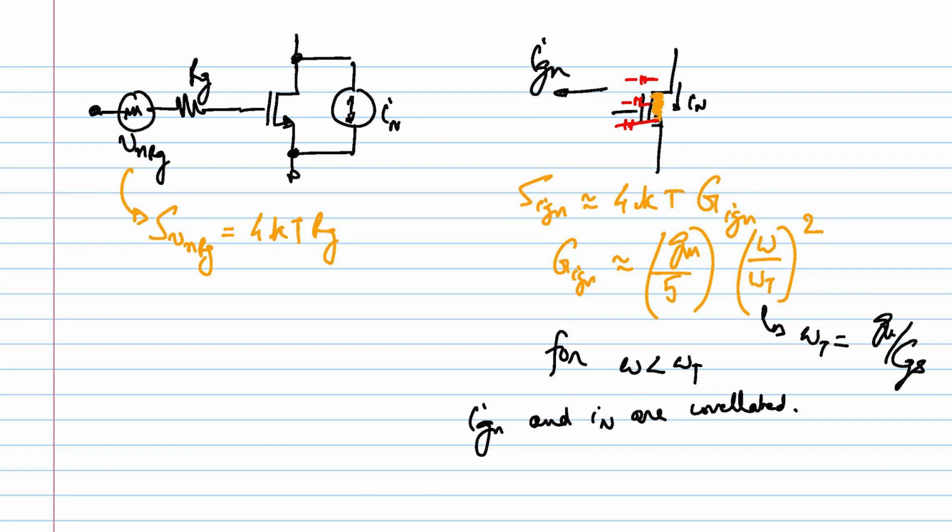Okay. So in the rest of today's lecture, let's take an example again for a common source amplifier. Put the effect of RG into account and then find out the noise figure at the output, right? So in the previous lecture we saw what happens if we input refer everything and find out the noise figure. That has some value, but as you saw, we have to deal with correlation, this, that. But if nothing is specified, you can take the noise figure anywhere. So we'll take an example of calculating the noise figure at the output, and you will see that it's fairly simple to calculate the noise figure at the output, in most cases. Okay.